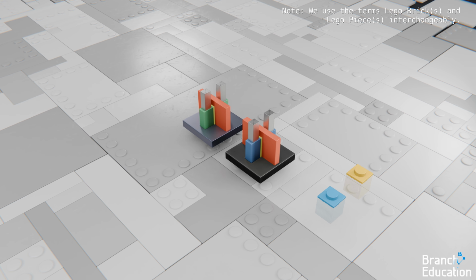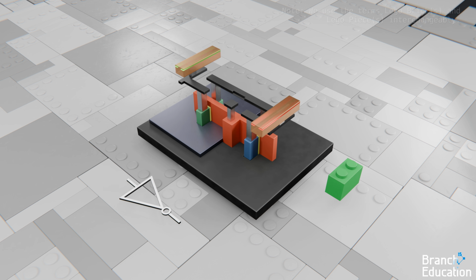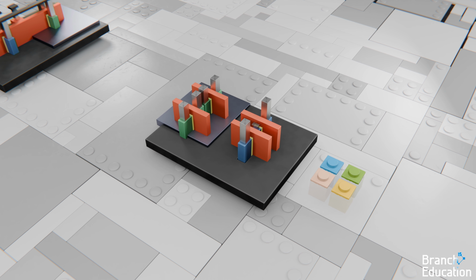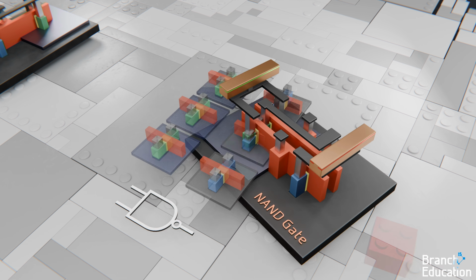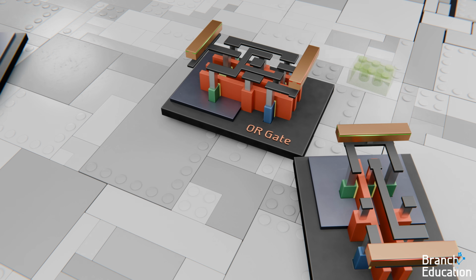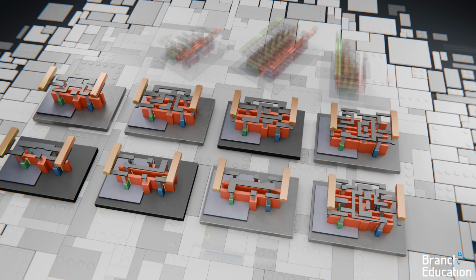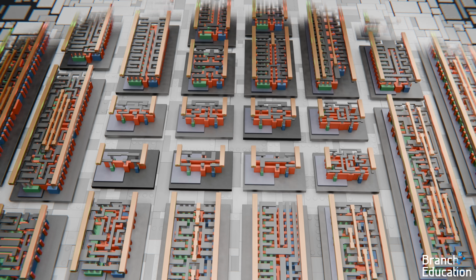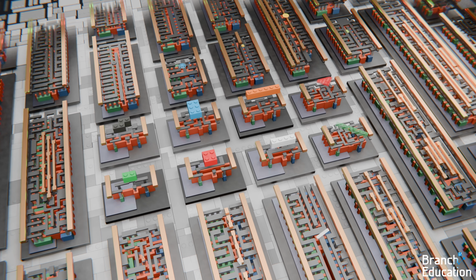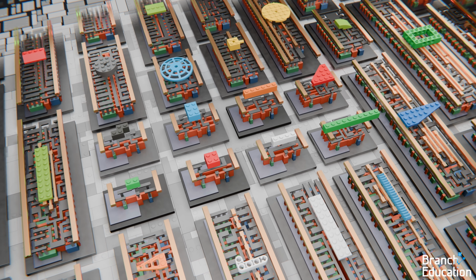For example, two transistors connected together form an inverter standard cell. 4 transistors connected together form a NAND gate, and 6 transistors form an OR gate. There are many other standard cells built by connecting transistors together, and similarly, there are a wide range of Lego pieces with varying numbers of studs and shapes.